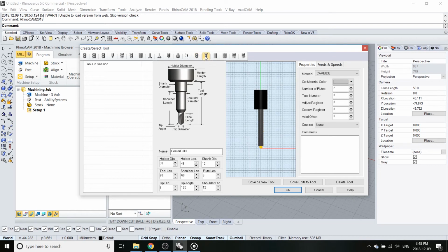A center drill is a typical drill bit with a taper at its tip. They are typically used to add precision to drilling small holes in contrast to a normal drill bit. Their use can be considered similar to that of creating a pilot hole. Reamers are used to enlarge existing holes as well as to create finer interior surfaces. These require a hole to be drilled in first that is close to the diameter to ensure that the reamer is not removing too much material.